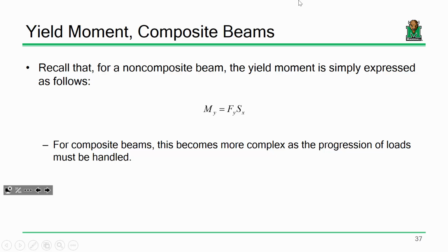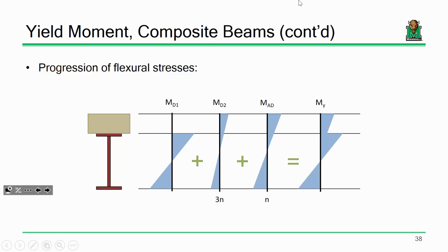And the easiest way to explain that is to look at this, okay? So what I have here is a composite steel beam and a bridge. So here's the steel beam, here's the deck. Keep in mind, conduct that thought experiment. What happens? I take that beam, I set it on the supports, I put the formwork, the cross frames, the studs, the rebar, and I pour the deck. All of those moments, the first stage of dead load moments, go just on the steel beam, right?